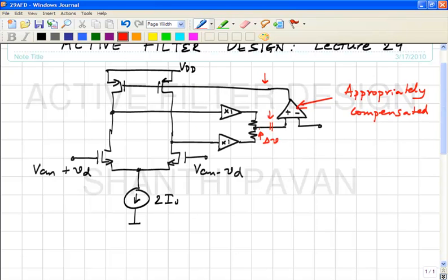Since you have two integrators in a loop, the closed loop response as far as the common mode feedback loop is concerned will have poles only on the j omega axis, so it will be unstable. And to fix this, what we said was we could Miller compensate, recognizing that this is nothing but a two-stage op amp in disguise. One thing that we could do was do this.